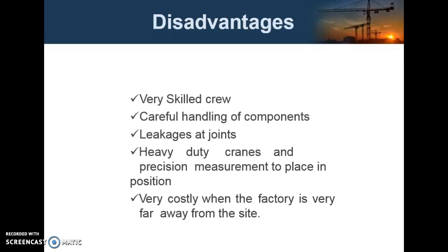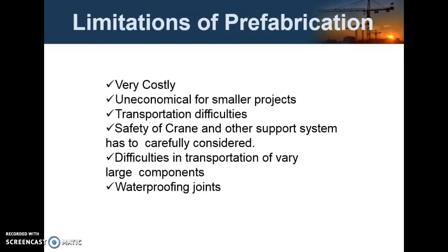Disadvantages: we need very skilled labor at the manufacturing site and at the construction site. Careful handling of concrete components is required. Leakage at the joint should be prevented. Heavy duty cranes and precision measurement are needed to place components in position. Very costly when the factory is very far away from the site.